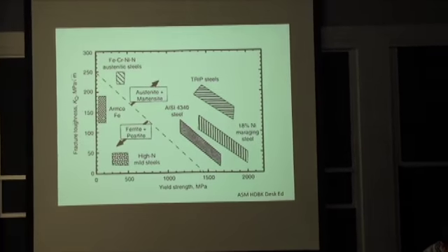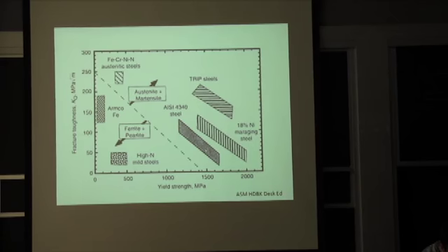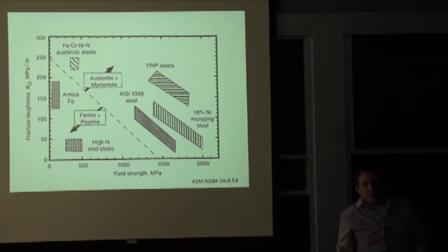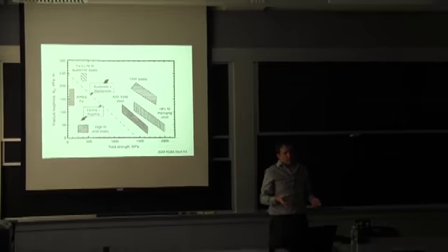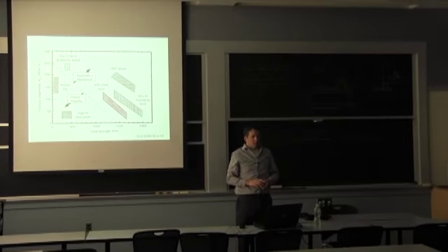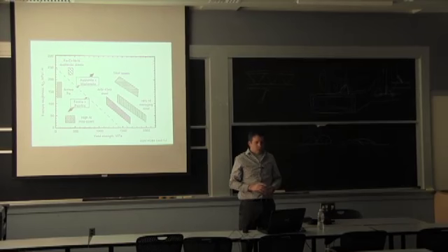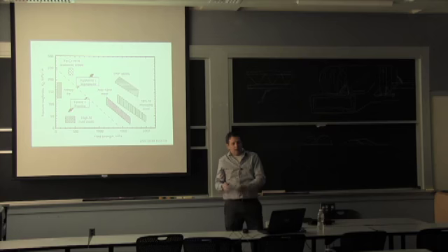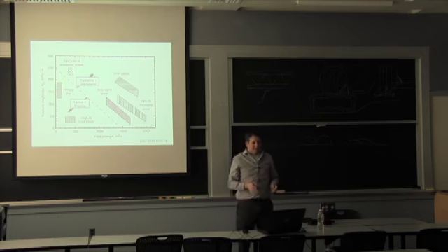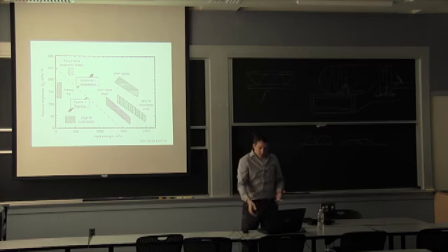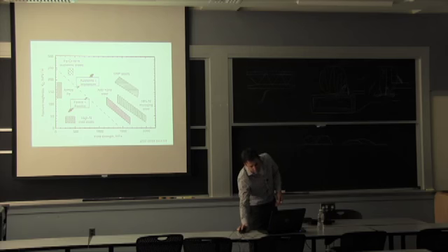Now we'll talk more about fracture toughness in the next class, but I do want to get all the way to what we call here TRIP steels, because it does tie into everything we talked about, that martensite transformation creating volume. It's a way to get both yield strength and toughness of a material. If you find a way to process your steel, obviously here it says you have 18% nickel, there's cobalt, there are different alloying elements.